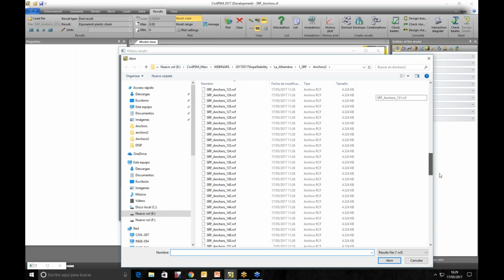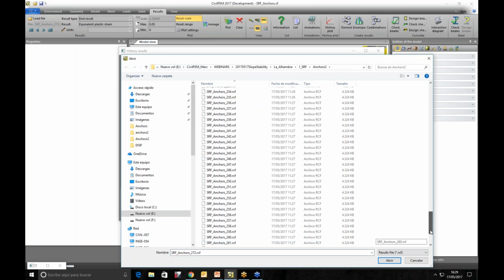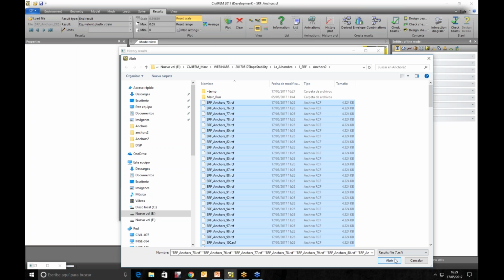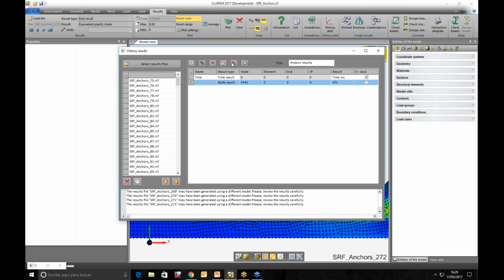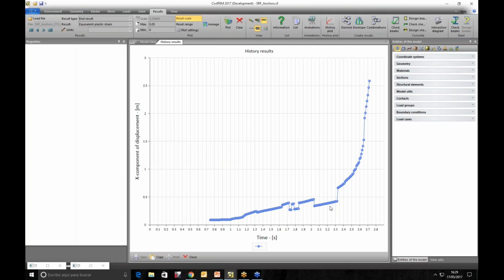And we are adding the new results that are here, to here, and we are plotting the displacements. Well, we can see here the displacements, just as the loss of stability starts happening, around 2.5, or displacement bigger than 1. We could determine an allowable displacement lower than 10-15 centimeters around here, so we can at least say that the safety factor is around 1.8, 1.9.